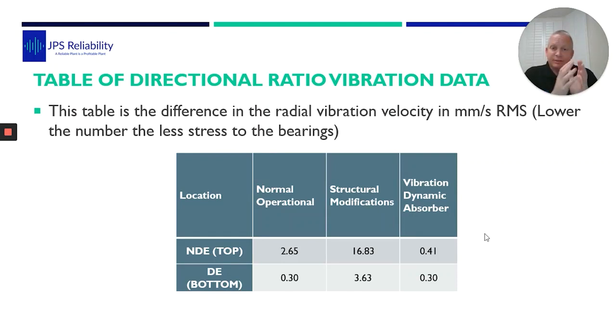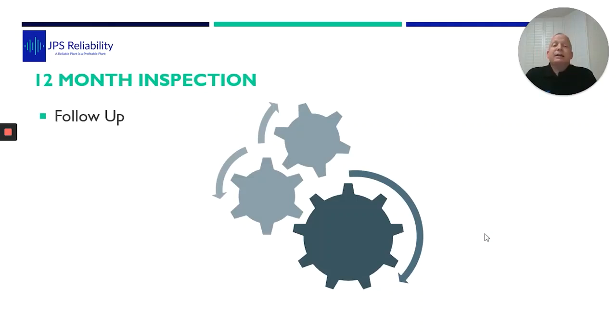Well, that was our theory, is that what we're aiming to do is absorb the energy. So we went back after 12 months, and they said to us, well, one of them's not working. So it's been going for 12 months, hasn't failed yet. So touch wood, we're looking like we are actually doing it. We're absorbing energy, and the problem was the whipping in the motor was stressing out the bearing, putting too much dynamic load to the bottom bearing.